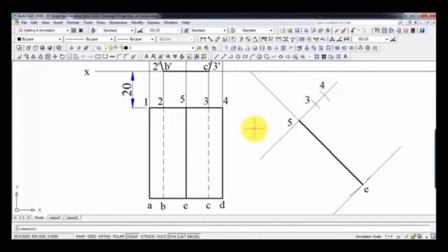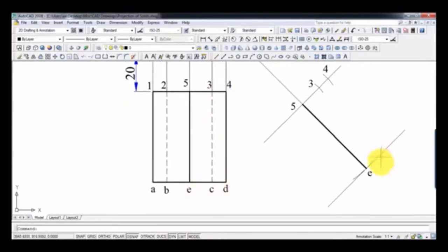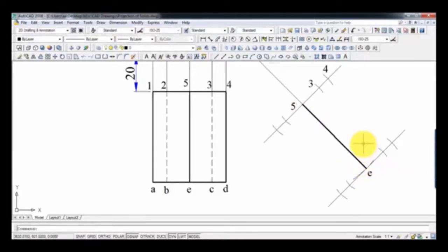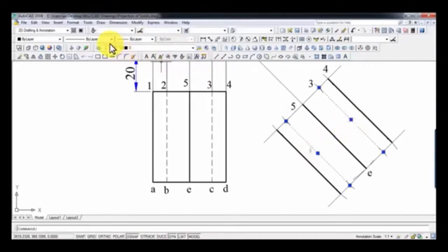Right? Okay guys, the next thing to do is to repeat the same process of putting up those arcs over here, over here, over here. I'm going to just copy this, and finally it should look something like this. All right, now let's join all these points. Now let us darken all these lines which are perfectly visible from the top, and these are what you call the hidden lines, broken lines. All right, so right now I'm going to chop off the portion which is not desired.